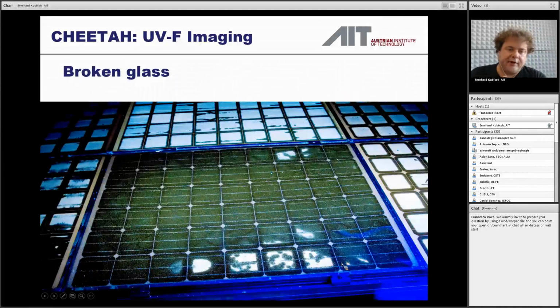And if you have the breakage of the glass, for sure you have additional diffusion even through the front side to the front layer of the EVA that you would typically see fluorescing. And it's extremely dampened, but not everywhere. Maybe this originates because in the lower section of the module, the glass is more pushed together and less diffusive. But also here we don't exactly know why you have fluorescence in the center of the lower cells, but not anymore in the upper cells.